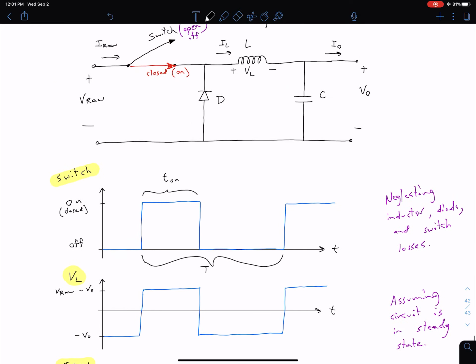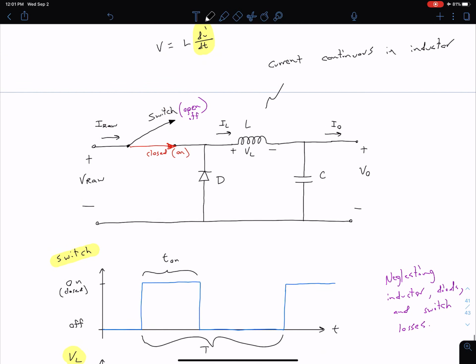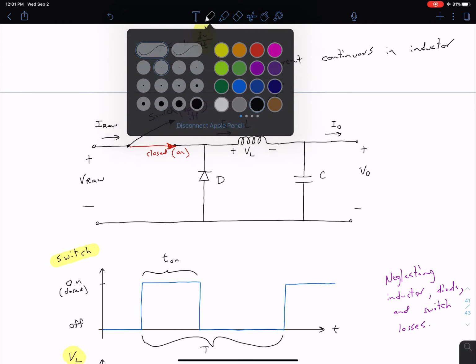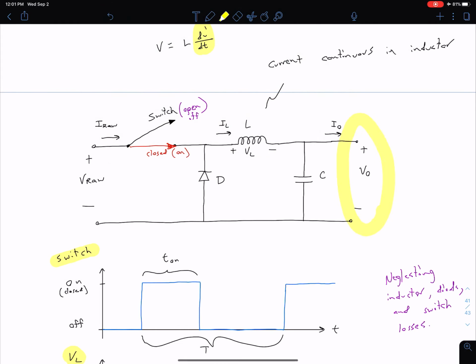So what's going to happen is, again, our inductor current cannot change instantaneously. So we know that if this inductor has already been charged up, the switch closes, it has some current in it, the switch opens, and that current is going to be dropping. We're going to be dissipating energy to our load. So we can think of having sort of a load resistor over in this area as our simplest case. So our inductor current is decaying away as we're supplying power to that load.